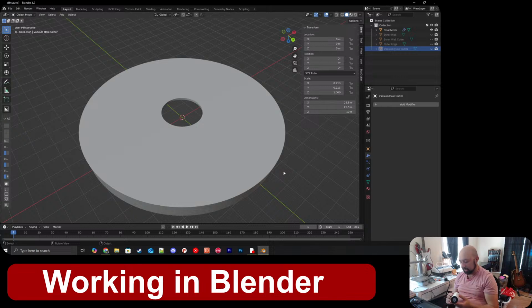It needs to have something that can fold up when the suction's on it to let air out, but then as soon as you stop the suction, the higher pressure outside will keep it closed. I don't know how to do that 3D printing it unless I put supports on this whole thing. I don't want to do TPU supports.